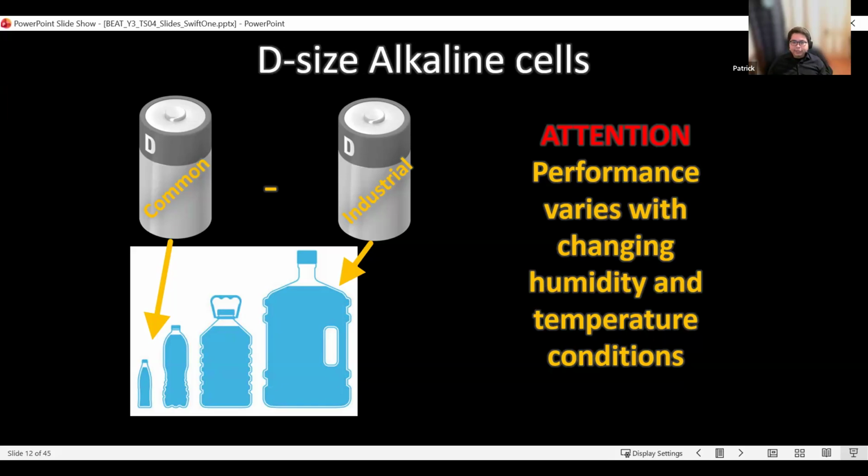So a lot of time in engineering, I do a 15%, 20% reduction in capacity. So if someone tells me, okay, this will give me 12 watt, then I reduce it to like 8 watt because it's always better to have more power than you think you do versus you plan too much and then it runs out. So something to keep in mind.